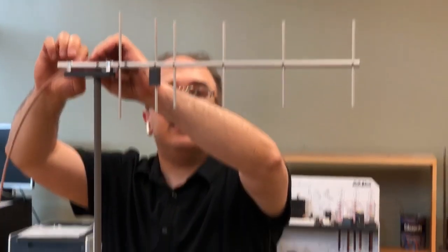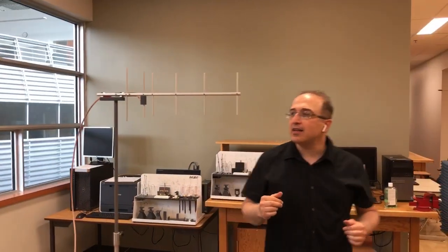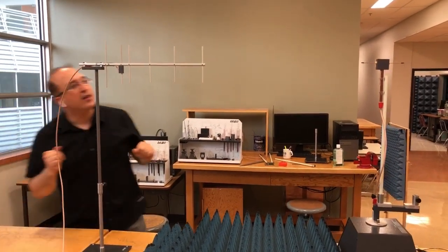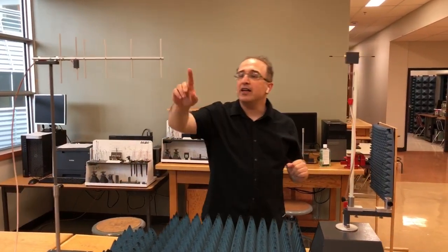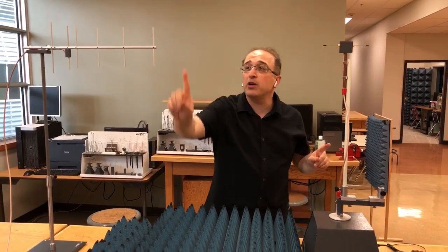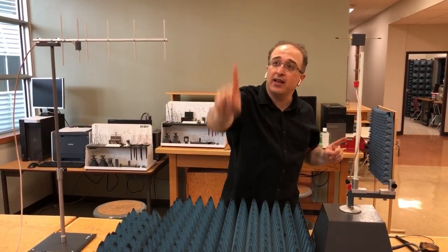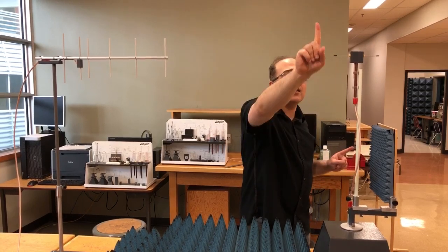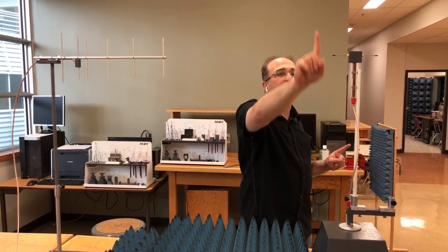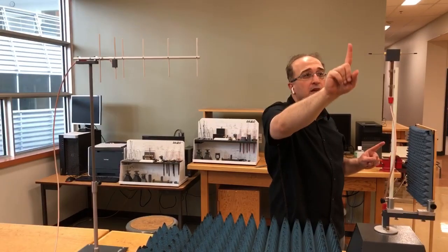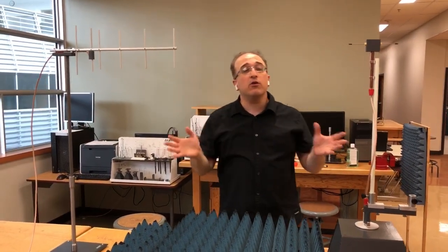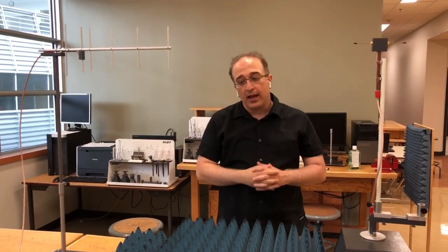Now, in this case, the situation that we have is that this antenna, let me make sure that it's almost 90. Yeah, so this antenna right now is again linearly polarized, but vertically. So this would be the electric field that's coming toward this antenna. But because this electric field is perpendicular to this dipole antenna at any angles, ideally you have to have zero reception at any angle.